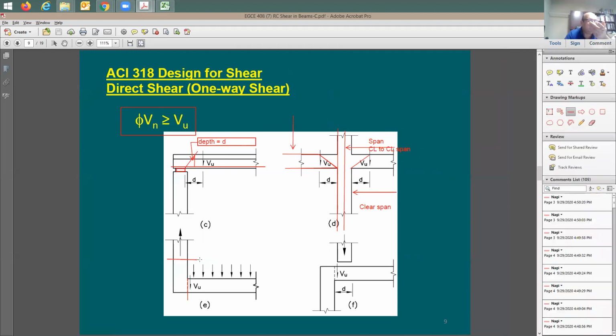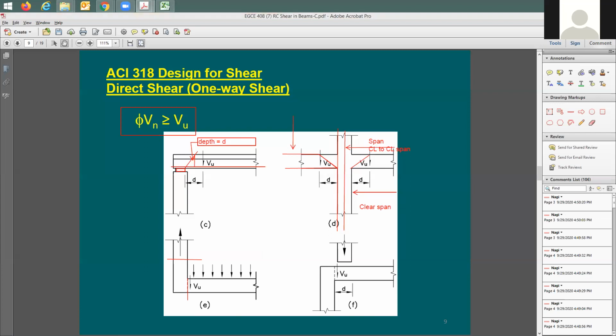So how do you figure out the strength of this column? Well, because the entire section here is exposed to tension, what you need to do is say phi Tn, which means the strength in tension of this column is going to be equal to the total cross-section area of the vertical rebar multiplied by F sub y multiplied by phi factor of 0.9. One of the questions that you're going to say, why 0.9? I'm going to say, hold on, you're not that far.